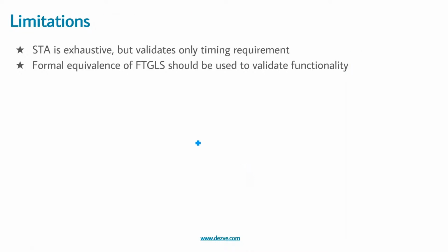Okay, now to summarize static timing analysis, STA, we have seen that in no case did we actually require test vectors, correct? Based on the launch path, the capture path, the data arrival time, and data required time, we were able to validate setup, hold, and similarly recovery, removal, and other timing checks as well.